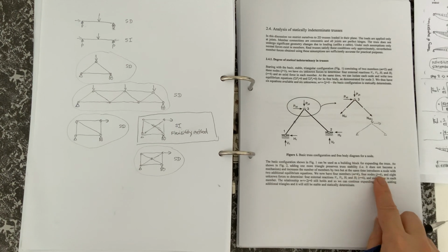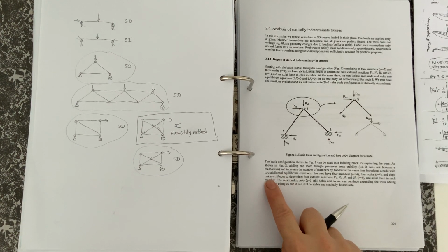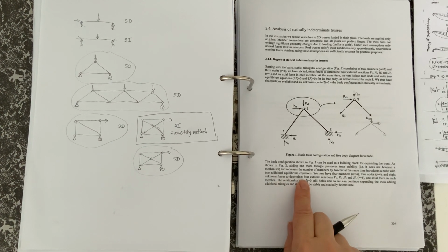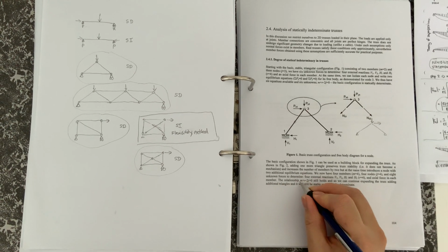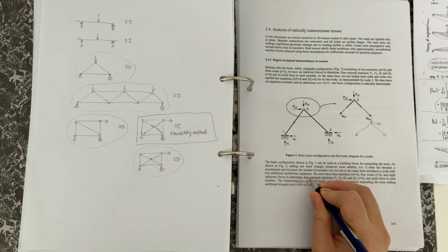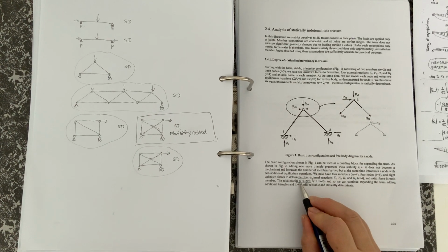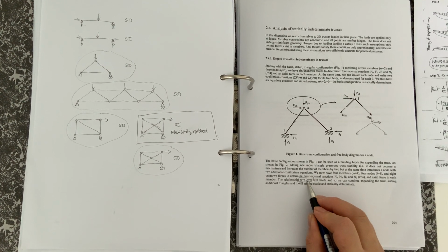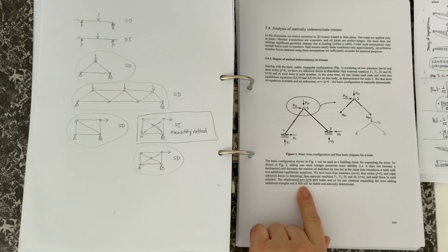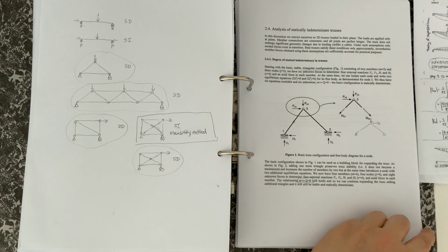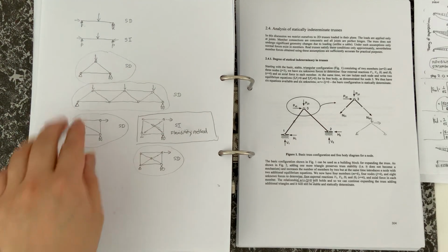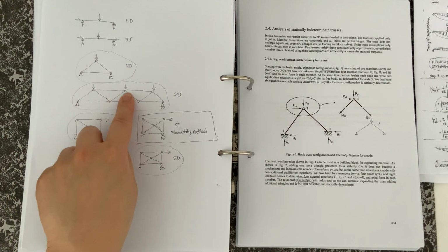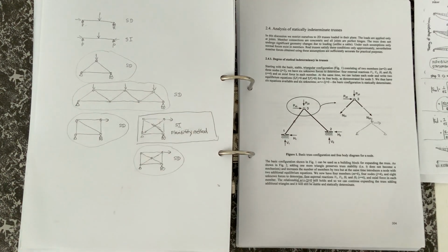We now have 5 members, 4 nodes, and 8 equations and 8 unknowns to determine, an axial force in each member. So that's the formula: number of members plus number of releases minus 2 times the joints. So use that equation if you really want to, but try and understand what's happening in terms of the building blocks of the triangular portion.